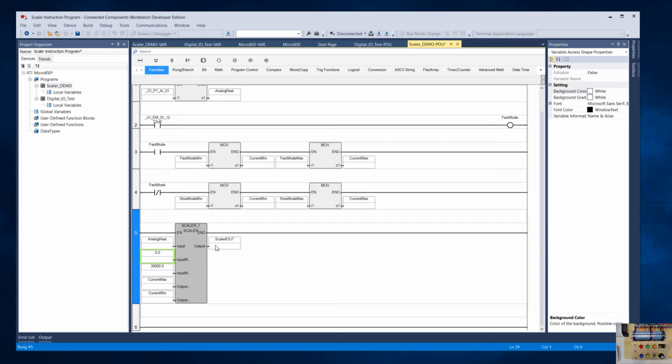So what we want to do then is a little bit of evaluation and math for the output. So let's say here I'm going to fake that example of doubling my input by limiting my range to 0 to 30,000. So before, my maximum output was based on a maximum input of 60,000 plus. Now it's going to be 30,000.